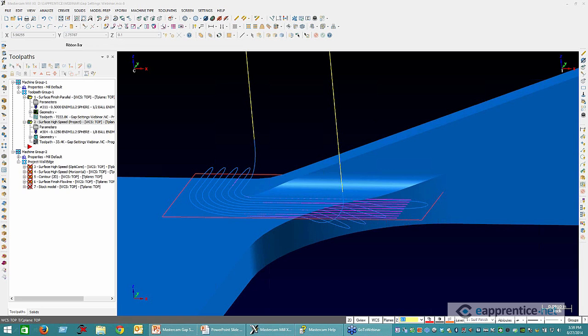And the other thing is, do you really need 90 degrees of tangential arc? A lot of times I'll try and go with like a 20-degree sweep, so I'm just barely retracting up off of that surface.